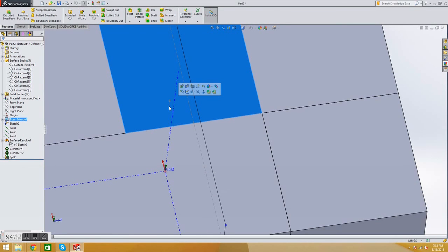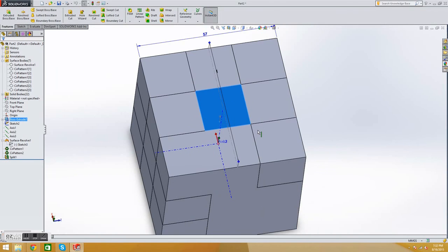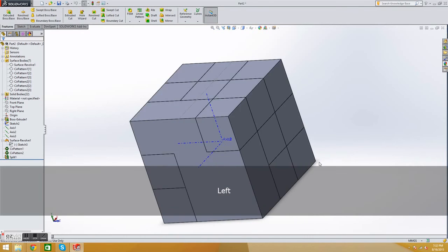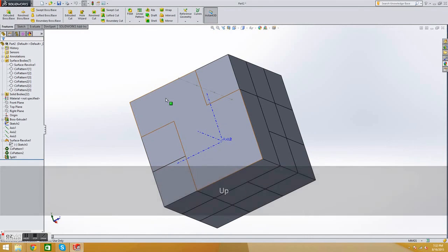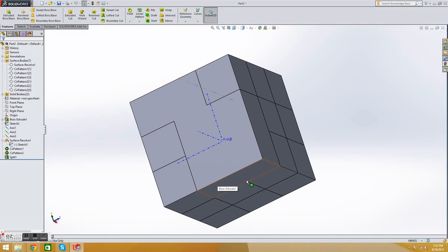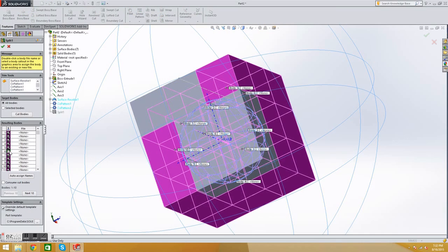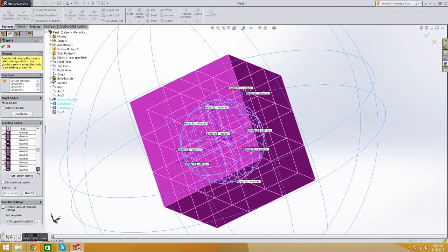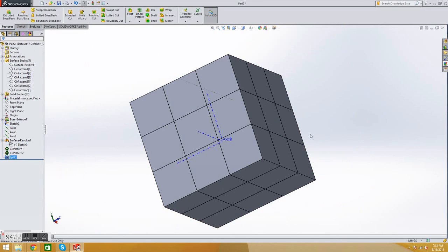And notice on these centers, oh gosh, this is important. Look at this. See how all of these are merged? That's because, remember when we clicked all those boxes back here on the split feature? Here, I'm going to click on split, edit feature. Because we changed the original sketch, it didn't understand some of the new lines. So we have to go back and click all the boxes that aren't clicked. Then you press check. Yeah, that is a little error.